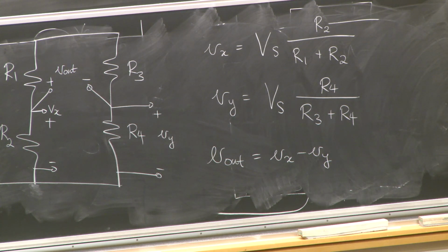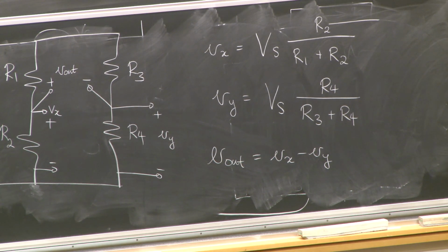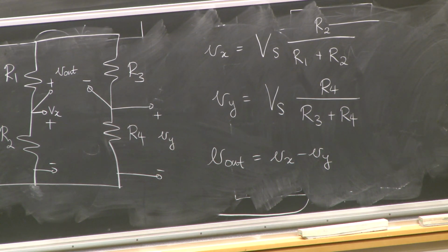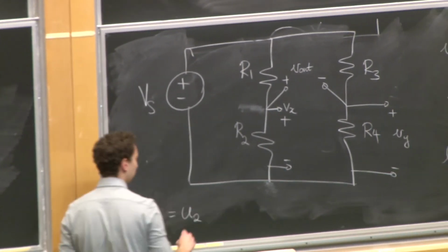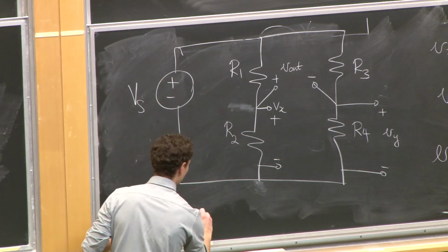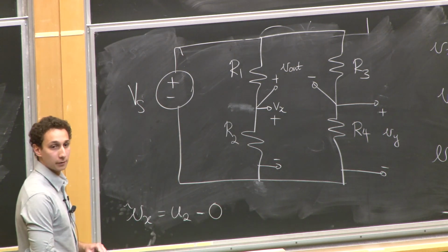Yes, I can. So there's two different ways of looking at it. One, you can look at it from a Kirchhoff's voltage law perspective. The other way you can look at it is the following. Implicit in these voltage expressions is a subtraction in potentials. So let's say I define this, just like I did in the nodal analysis problem, as some potential related to ground. I'm going to say Vx is equal to, I think I labeled that node 2, node 2 minus 0, right?